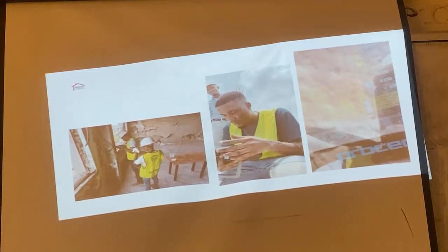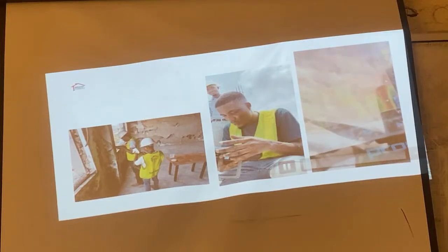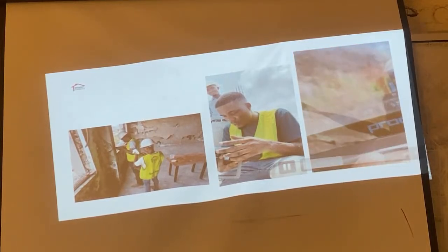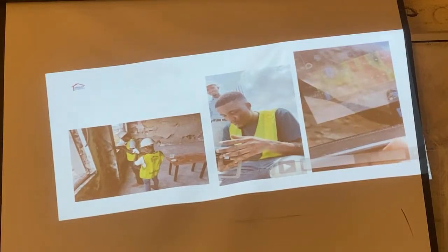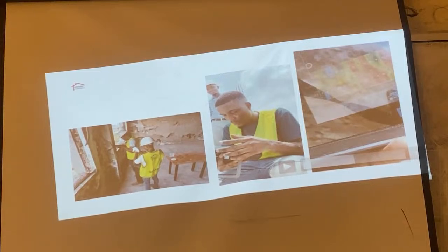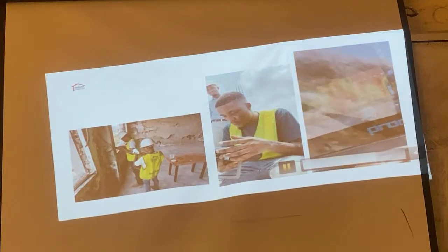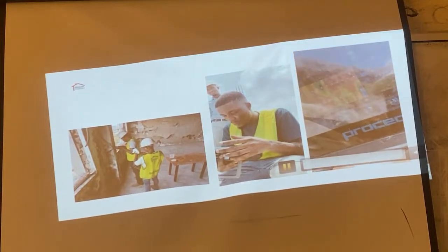All right, and this is a short video I'm going to play. I'm not sure if it's very clear, but hopefully this is what the machine looks like when we are trying to check for homogeneity of concrete. We're testing a concrete structure 6 meters wide and 4 meters high, a square structure to put a submerged pumping device. We're trying to check if there are voids inside that concrete.